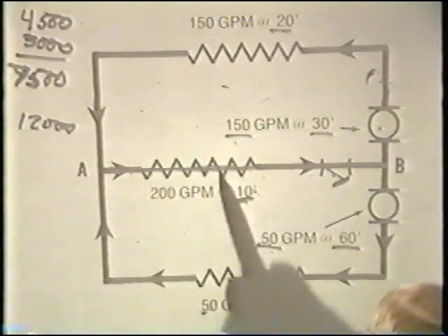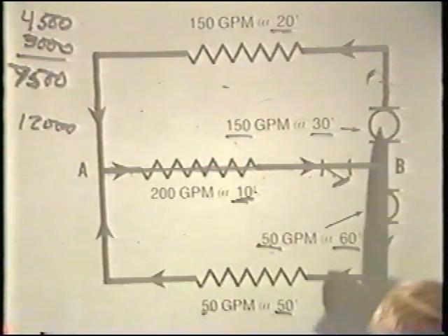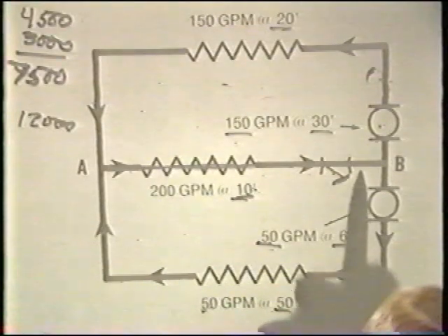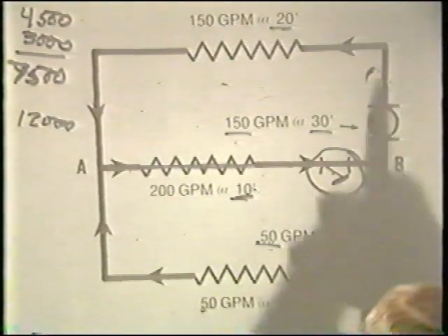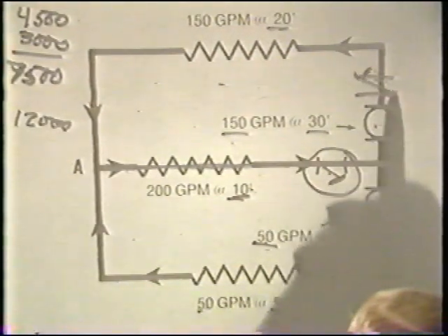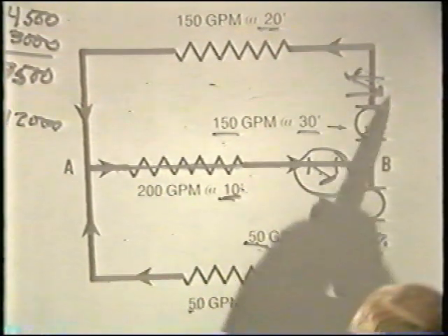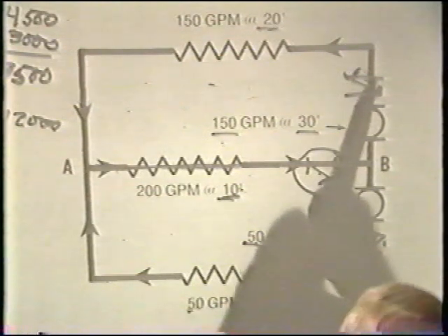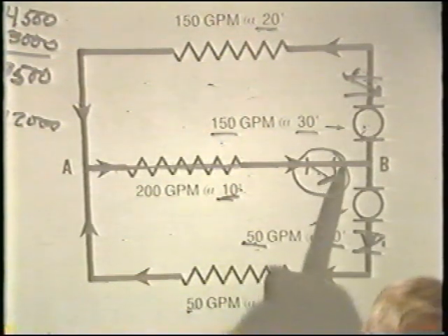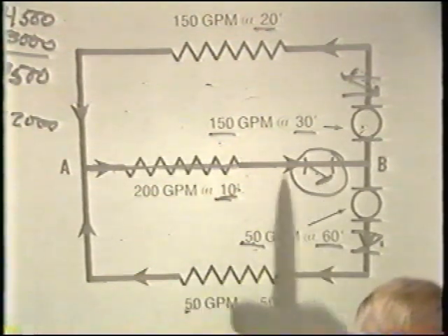This is because the common piping head loss is common to both pumps. And should that strainer become clogged, a check valve installed at the discharge side of the low head pump may close because of back pressuring through the clogged strainer.